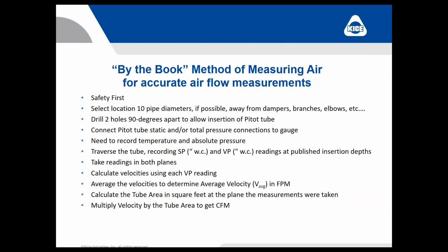So, by the book method, again, my apologies to engineers, but everything starts with safety these days. I've said select a location 10 pipe diameters away. Some of the newer books call out 20. They'll typically drill 2 holes 90 degrees apart, and our engineer just recently let me know that that's changed, and an engineer who's doing it by the book will actually drill 3 holes 60 degrees apart and take traverse readings of that tube across 3 planes of that duct.